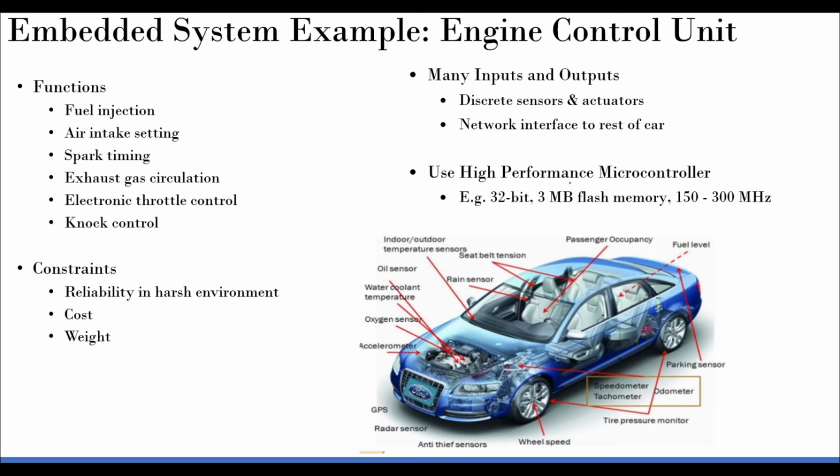And then, of course, in this case, we have a little bit of luxury, and we may need a little bit of luxury because of the safety critical aspects of many of these systems. So you do go for higher resolution and higher precision and higher accuracy. So you may go for a 32-bit with some internal memory with a higher speed of operation. So you need basically a higher performance embedded system compared to that of a bike in the previous slide. Okay, I hope it's clear.